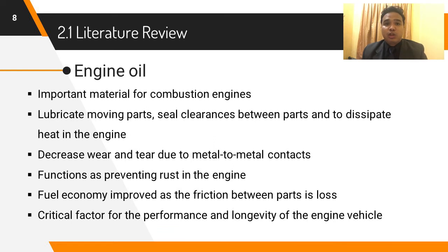Next is the engine oil. Engine oil is an important material for combustion engines. The engine oil helps to lubricate the moving parts, seal the clearances between mating parts, and function to dissipate heat in the engine. It will help to decrease the wear and tear due to contact between metals.